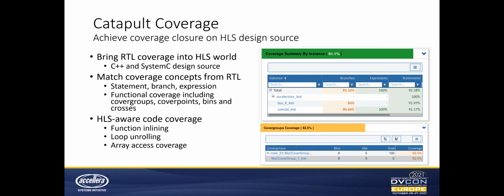From a hardware code coverage perspective, just knowing that you exercised that entire loop in C is typically not good enough. You want to make sure that each iteration of the loop was fully exercised, especially if there are branches, or conditions within the loop that will behave differently depending on which iteration of the loop that you're in.